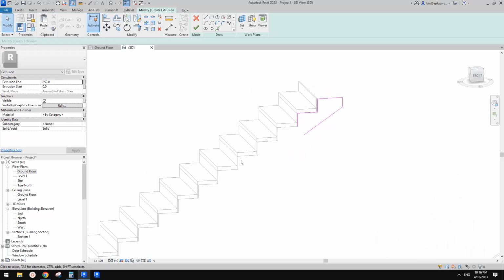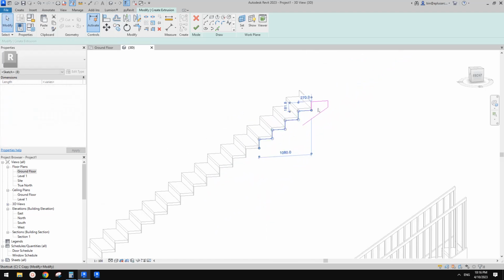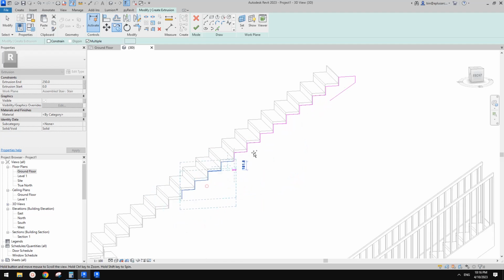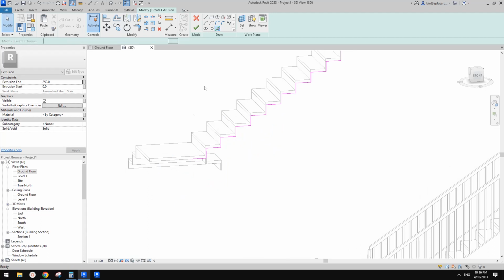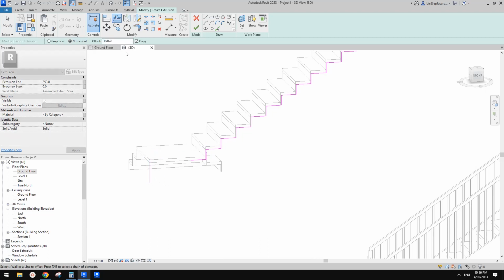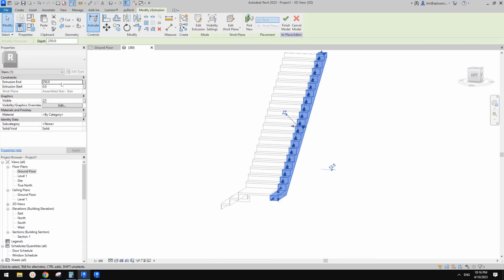And then you just need to pick all these lines, but you can also just copy and paste, right? Ctrl C copy, and then okay, so that's all. Finish at this point. So drag this down, offset the thickness of the landing. So let's just make it 150 as well, and then trim all the way up. And then because we know that's one meter, if it's not 1 meter, it's -1 meter.